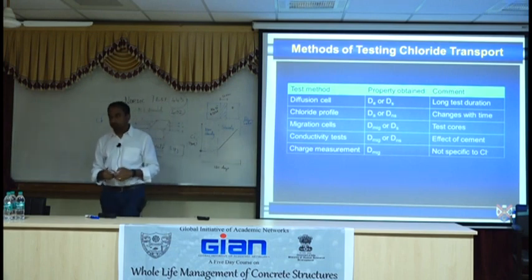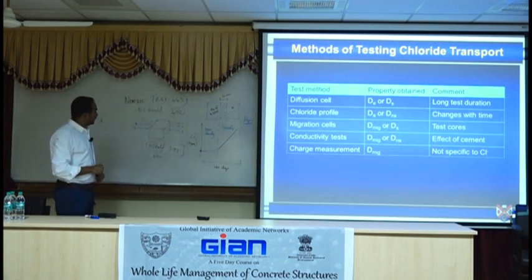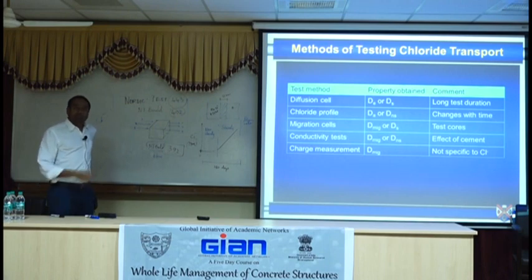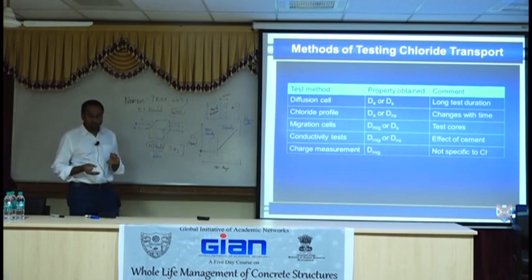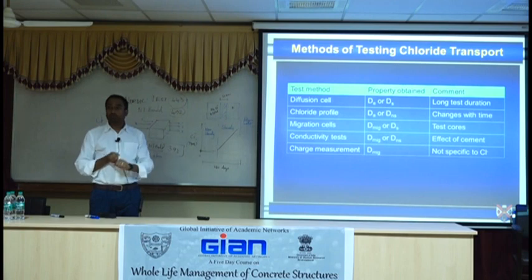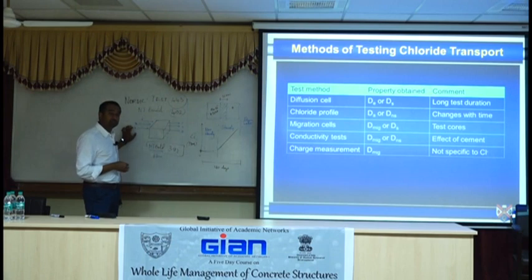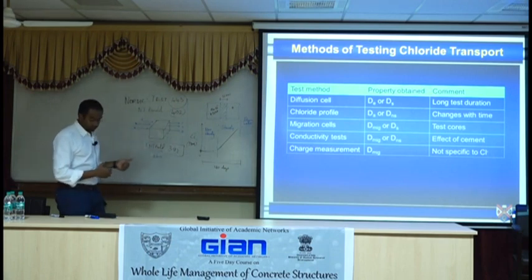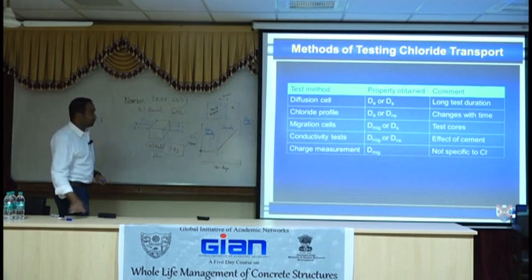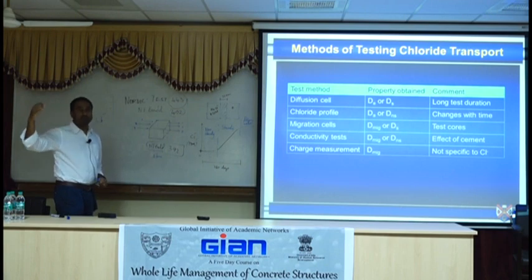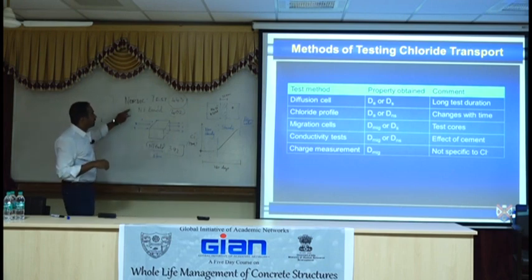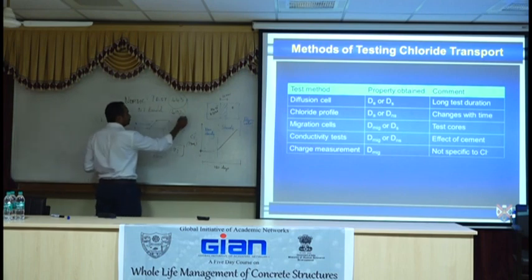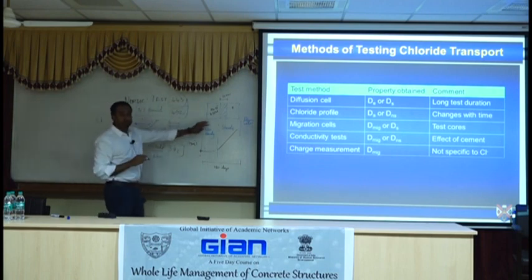Okay. It's a very long, elaborate test. But along with those standards, there are also standards for how to drill into concrete and how to analyze chlorides using different chemical analysis. So all of those standards are free. So if you are using or referring to something, use that. Some of the projects we have done in Europe for what's classified as performance-based tests, they're recommending to use 492. 492 is very similar to this test.